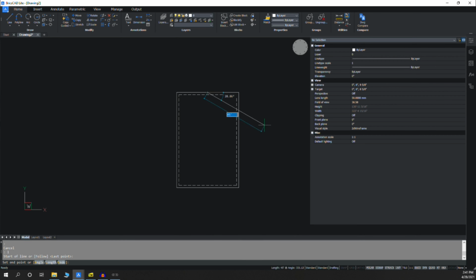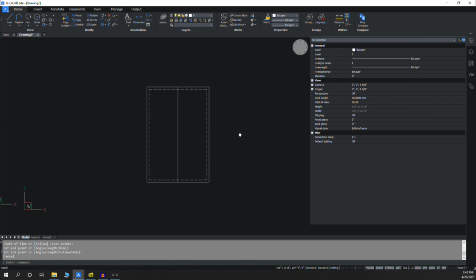If it's a gable roof, all I've got to do is draw a ridge line and you've got your plan. If I wanted to draw a hip, roofs are almost always 45 degrees. You can click on one of these corners and have it snap to 45 degrees, or you can hit tab and type in 45 degrees manually. Then I just draw a line.